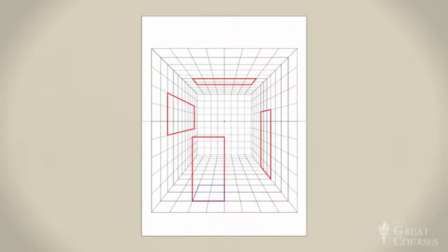To finish the box, draw receding lines toward the vanishing point from both top corners. Then, bring a vertical up from the footprint's rear left corner. Let this intersect the diagonal above it. This point defines the box's back edge. Now you can draw the back edge of the top of the box and erase the last construction lines.